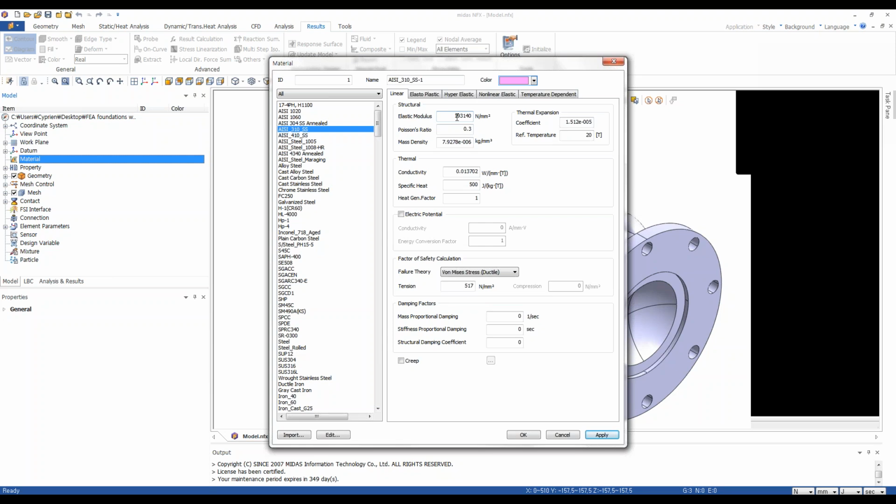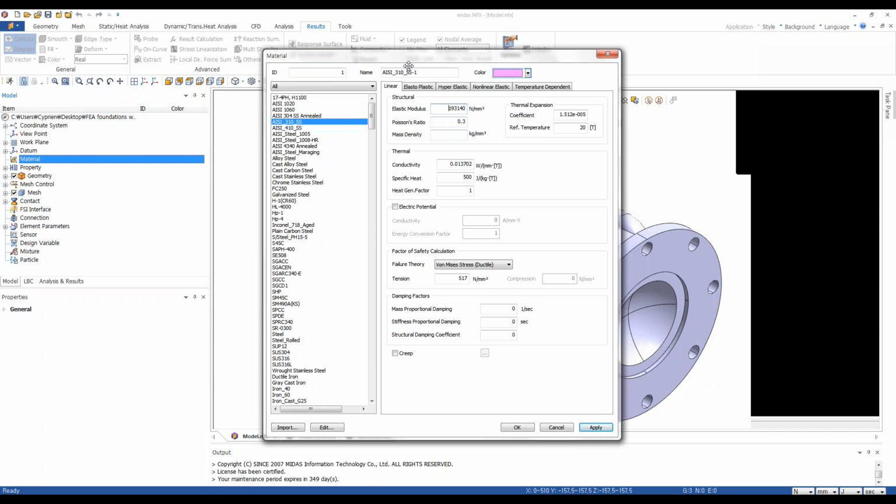As Cyprian said before, we are in a linear range, so for our model only two structural parameters are required. This is because of the assumption that there is no gravity acting on my model. If we take a look at this part of the material card, we have structural parameters, so we have to provide input for elastic modulus and Poisson's ratio only. So we can skip the mass, and this is why I will erase this data, and let's leave those inputs because they are good. My material will refer to steel.